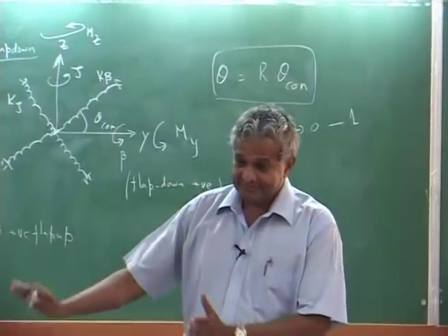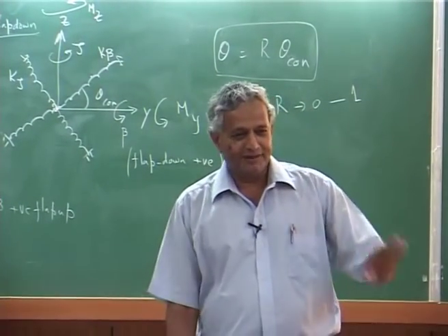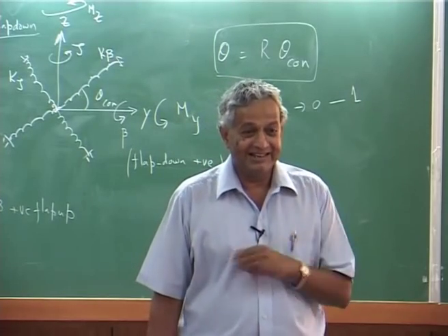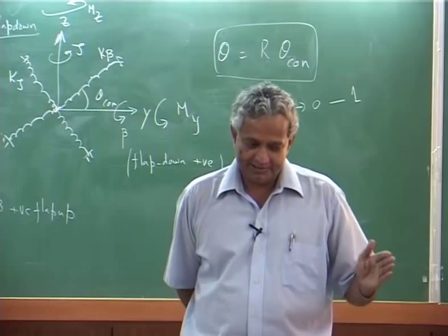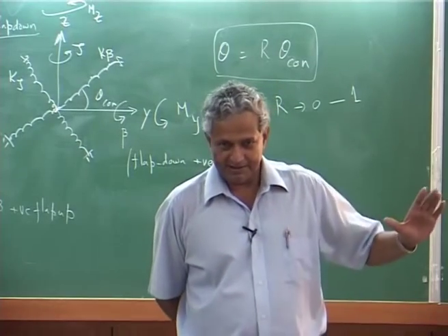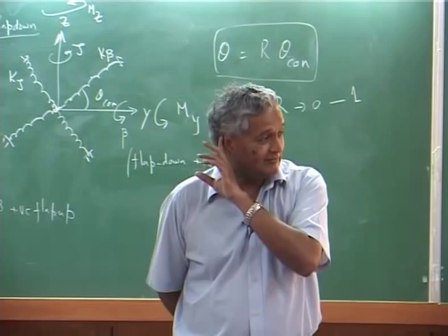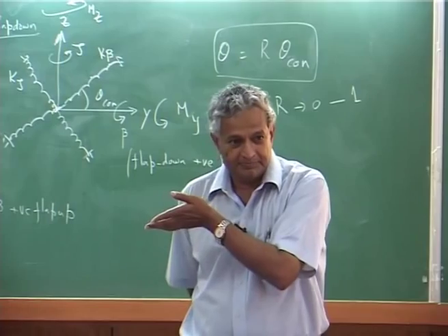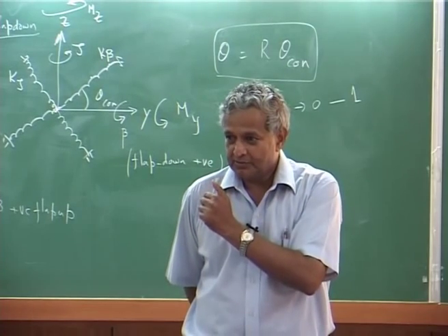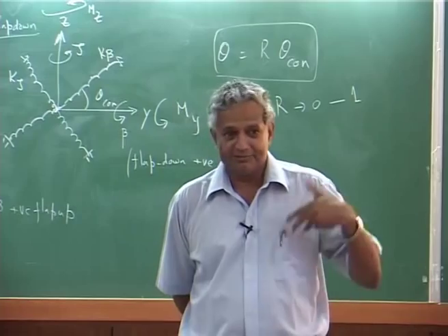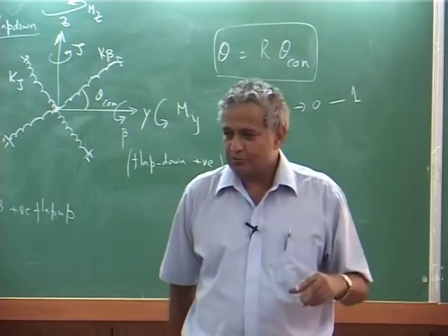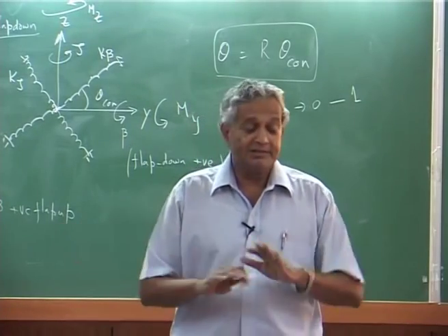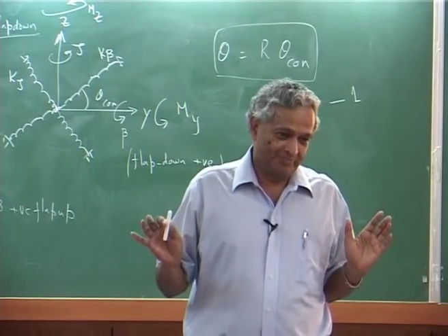All along, in the full course till now, we were concentrating only on flap motion, only flap. We never bothered about lead lag motion. Actually, as a subject, in the dynamics of the helicopter, flap is very important, but lead lag creates more problems, okay, but you cannot avoid it. So, you have to consider lead lag. Lead lag will come into the picture. Then of course, elastic torsion. So, that is why flap, lag, torsion, that treatment is the full dynamics, okay.